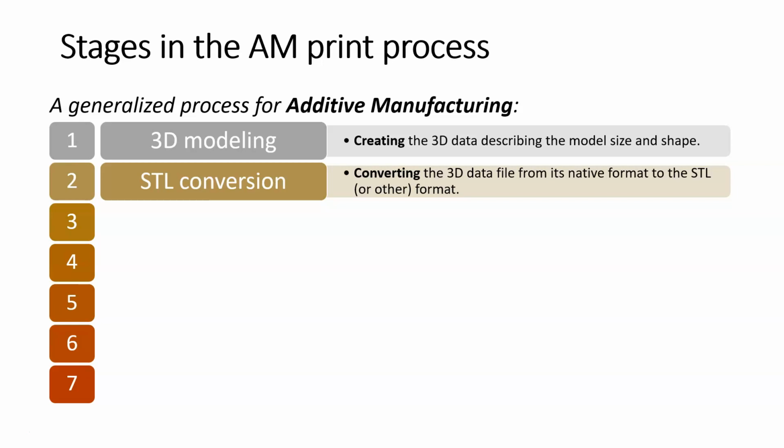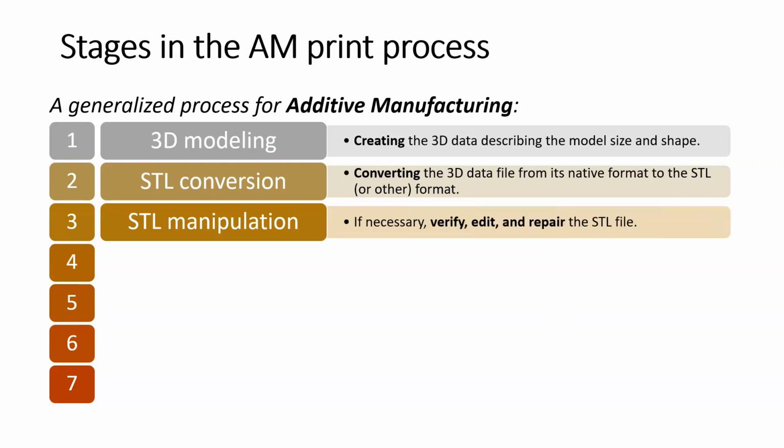So, and we'll talk about what exactly is going on with an STL file, but that's what an STL conversion does. Third step is we may need STL file manipulation. Okay. Now this will involve verifying the STL file, editing, or even repairing the STL file.